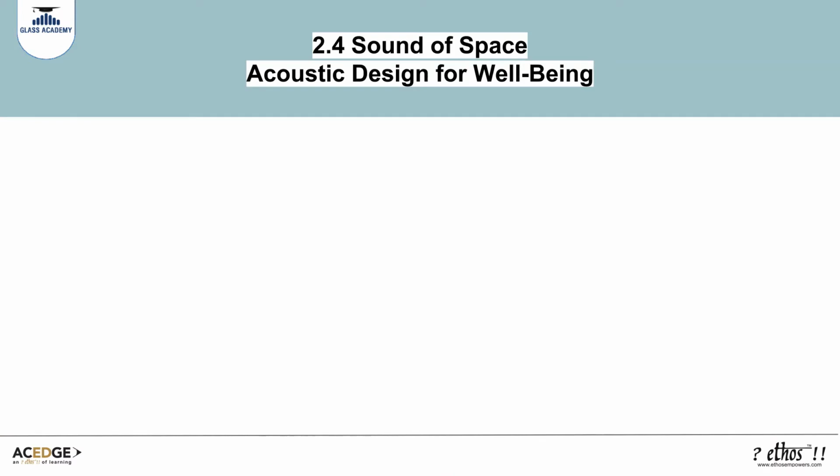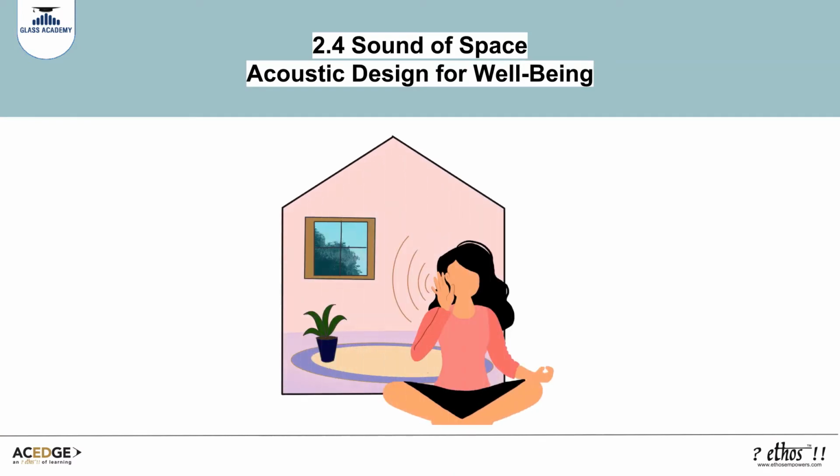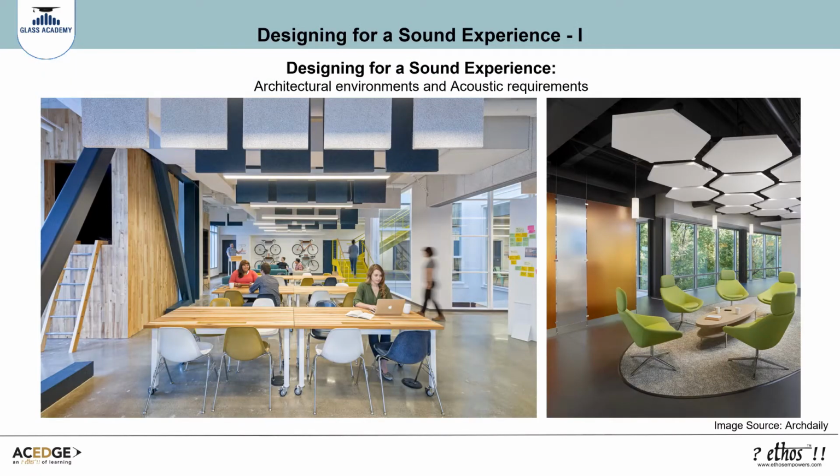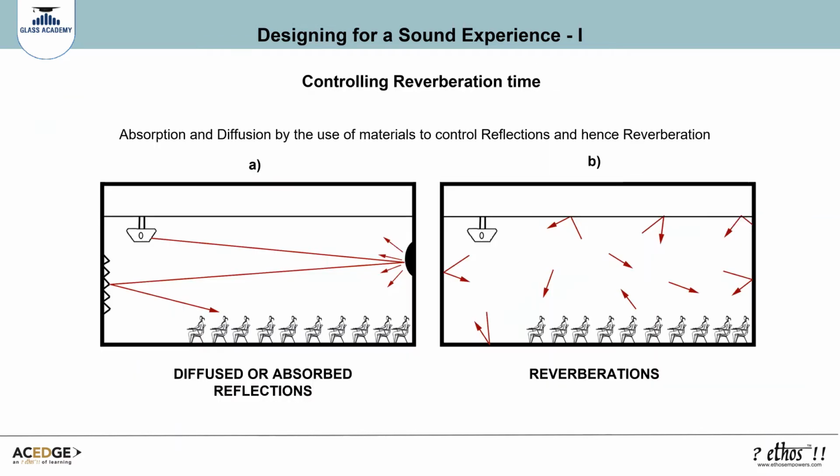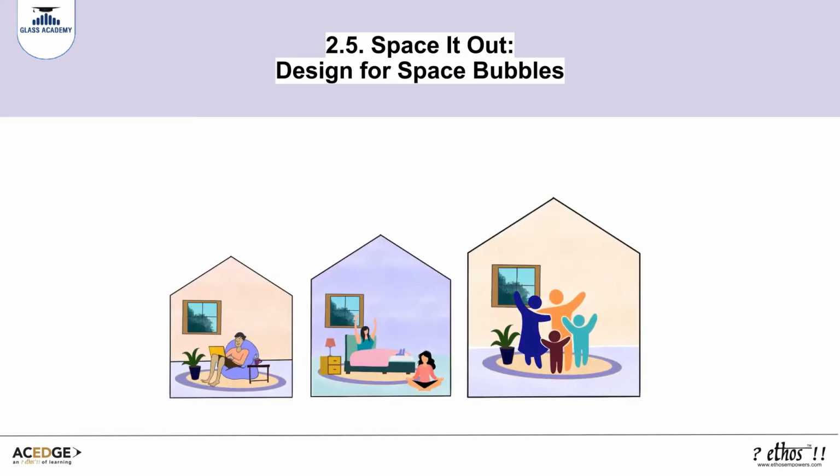The choice of building materials inside a space can impact the acoustic resonance and comfort levels. Absorbent ceiling tiles and other absorbent materials available in the market could be used appropriately to modulate reverberation time for acoustic comfort. Different techniques can be used to reduce or raise reverberation levels. It is important to design spaces to human scale as well as to create an ambient environment.